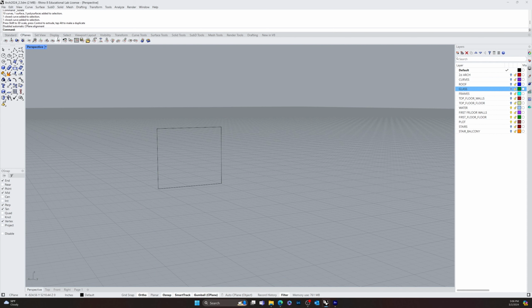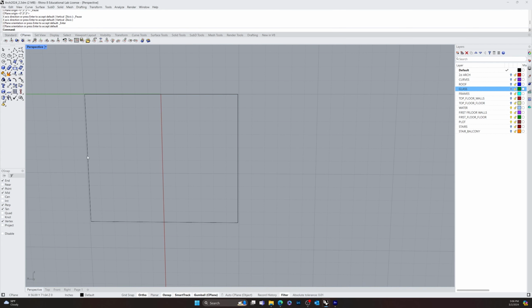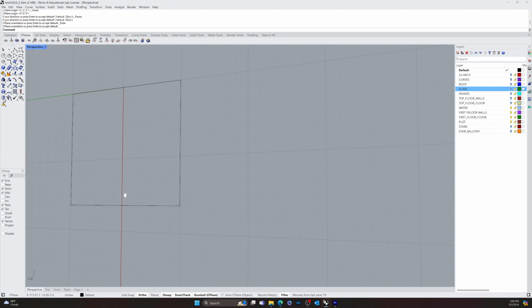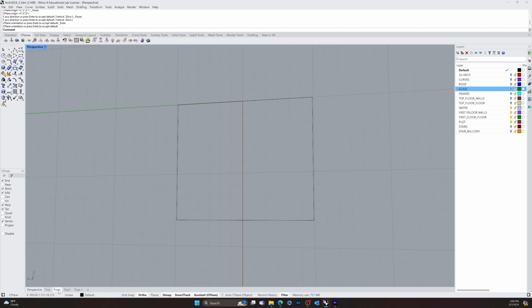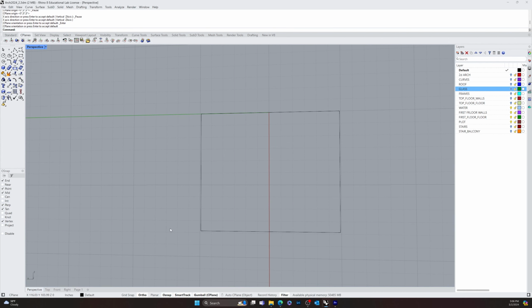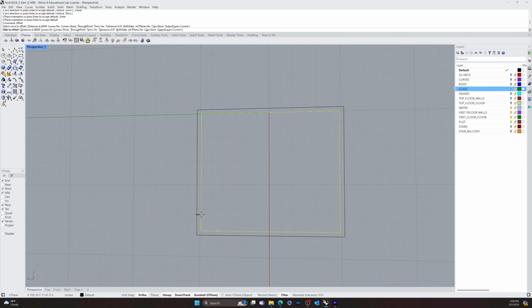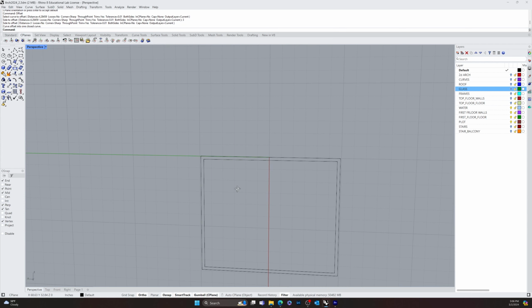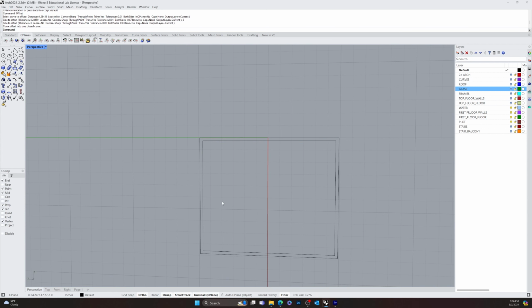Okay, I'm turning auto C-plane off, and then I'm going to set the C-plane. Under C-planes tab here, just go to 2, and I'm going to go mid, perp. Okay. Now I don't have to worry about the auto C-plane happening whenever I'm doing geometry. And yeah, let's go ahead and offset. And let's go in 3 inches. Yes. Click. All right. So that's going to be the overall frame. And I think I'm just going to start drawing some lines, straight lines, with the near.